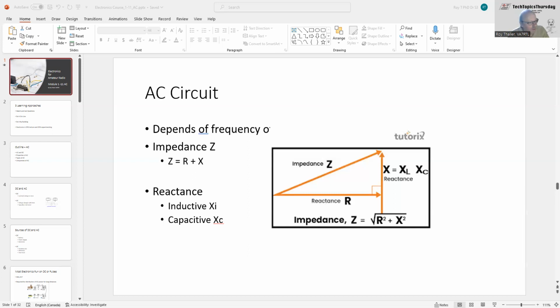In the advanced course we'll be covering some of this, but this is just to show you that it becomes more complicated. The capacitive reactance and the inductive reactance cancel each other out. This is, for example, what you do on an antenna tuner. You see what the capacitive reactance is and match it with an inductor, or see what the inductive reactance is and match it with a capacitor to cancel this out, and then transform the impedance so that it matches the output impedance of your radio. And again, we'll cover this in more detail.